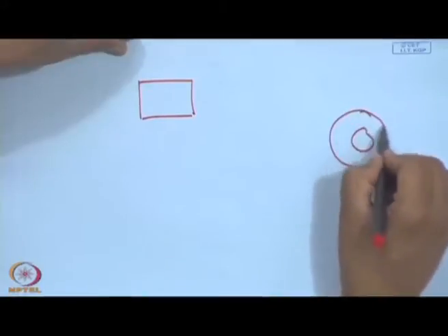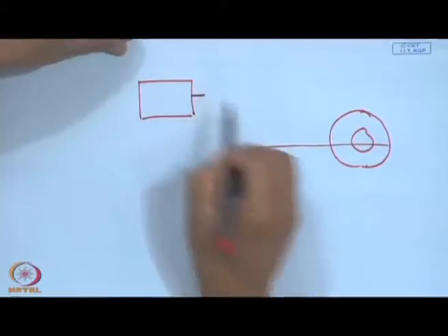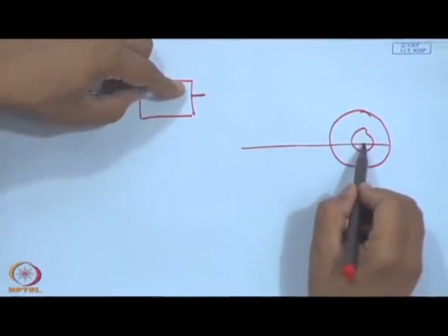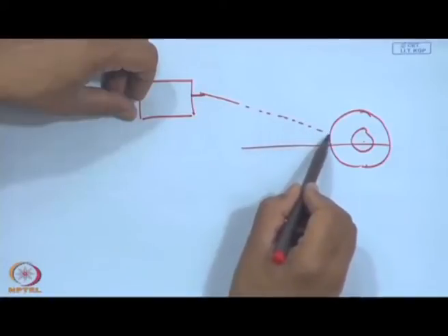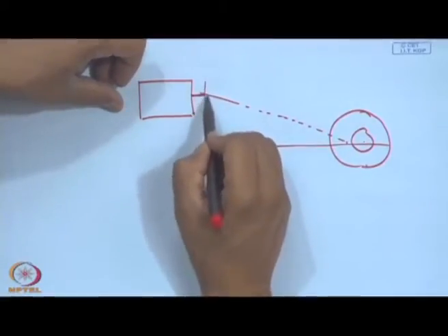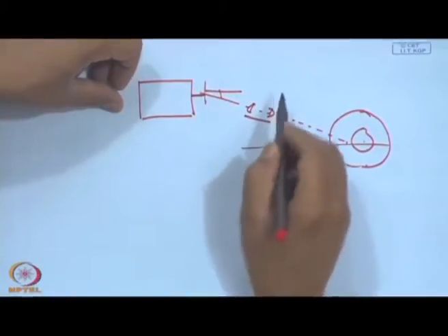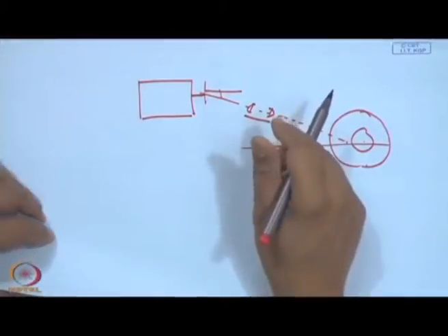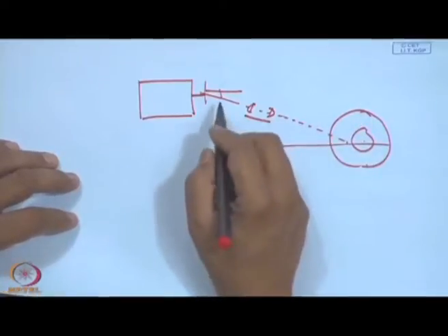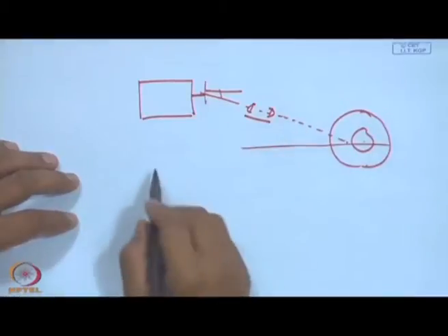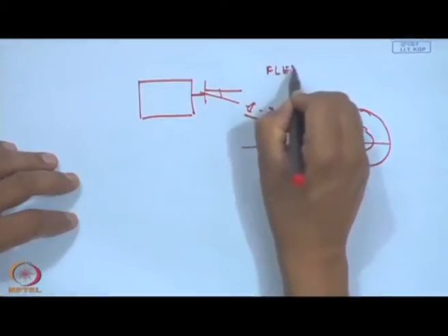For example, in an automobile propeller shaft, the reason we give a Hooke's joint is because if this is my wheel and engine is here, my output shaft is at a higher location than the driving shaft axis. So, to account for this kind of angular deviations, we have to give a coupling which can take care of it, and that is what is done by the Hooke's joint or the universal joint. So, misalignments are sometimes required and sometimes they have to be reduced in a rigid machine, and that is where the coupling stiffness comes into account. So, that is why we have the flexible coupling.